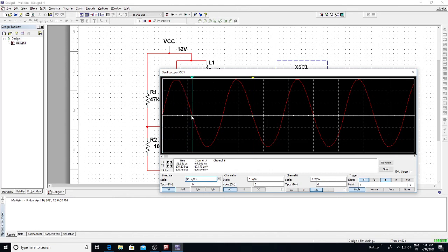Okay, at the same point where the cycle ends, we need to place it at the same points, T1 time period and T2 time. This is T2 minus T1 now, 482 microsecond. It's the time period for the capacitor value 0.033 microfarad. So this is the practical time period which you have got.